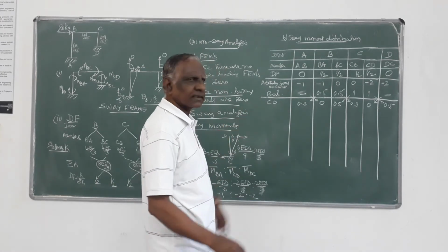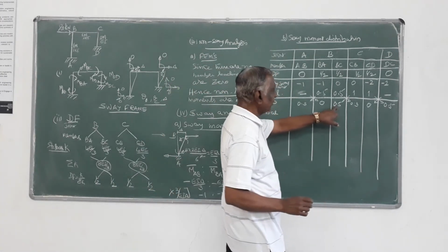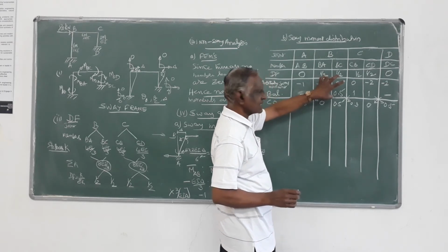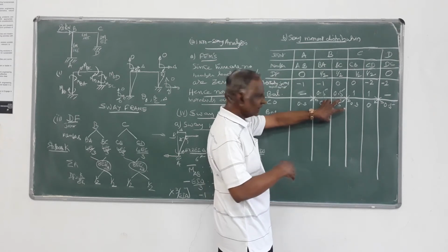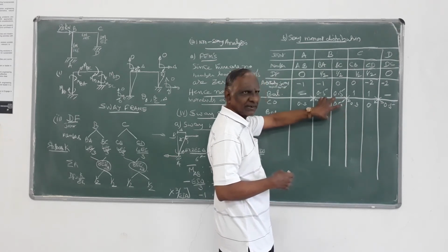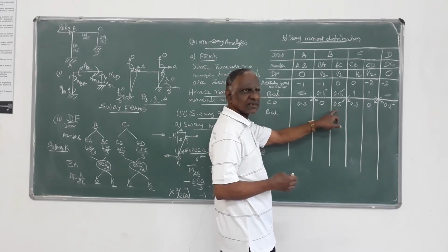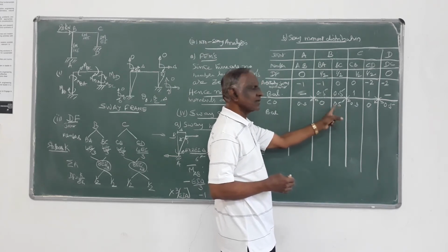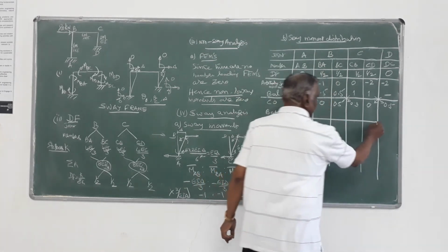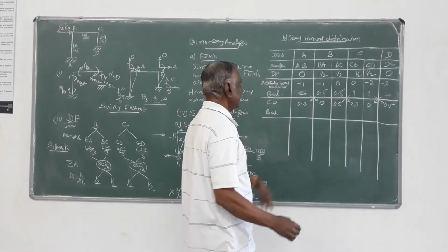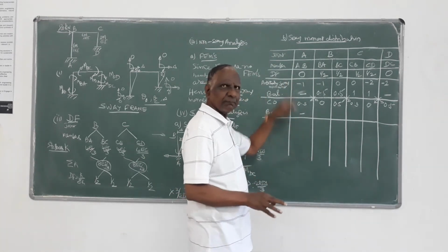So this is carryover. Next, because of this carryover, whatever balancing or equilibrium you had satisfied is nullified now. Here the equilibrium condition is not satisfied because the sum of the moments is 0.5 now. Again you have to do the balancing work. So again repeat it. At AB no balance because that is fixed, same procedure.